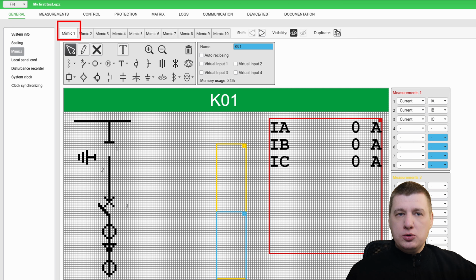The relay supports up to 8 freely selectable measurements on the mimic view. After configuration, you read those values on the local panel. Typically, the refresh or automation cycle update stays under 1 second.